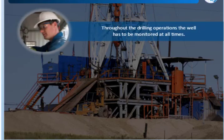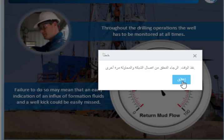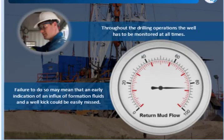Throughout the drilling operations, the well has to be monitored at all times. Failure to do so may mean that an early indication of an influx of formation fluids and a well kick could be easily missed, and so the opportunity to take fast, effective action is lost.